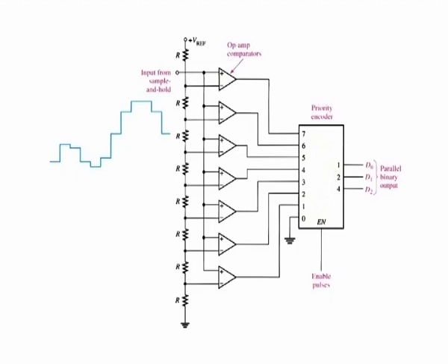The frequency of the enable pulse and the number of bits in the binary code determine the accuracy with which the sequence of binary codes represent the input of the ADC. There should be one enable pulse for each sampled level of the input signal.